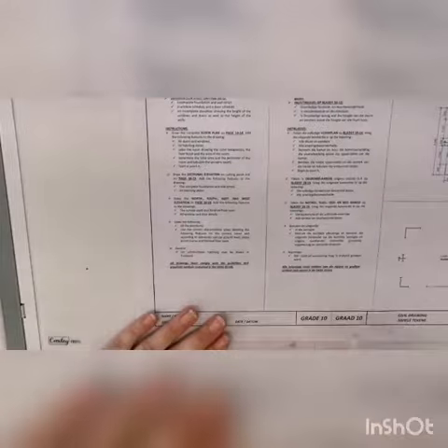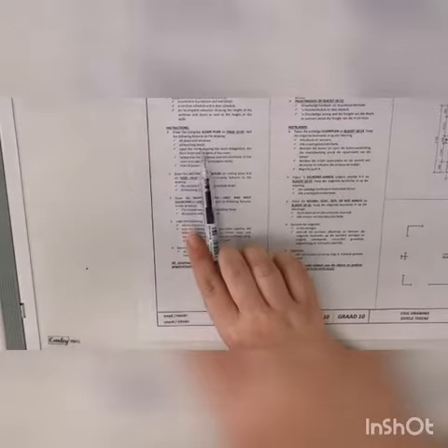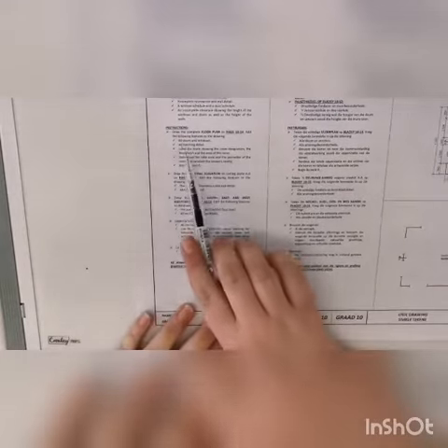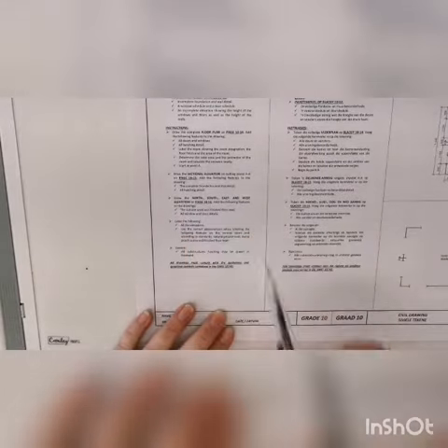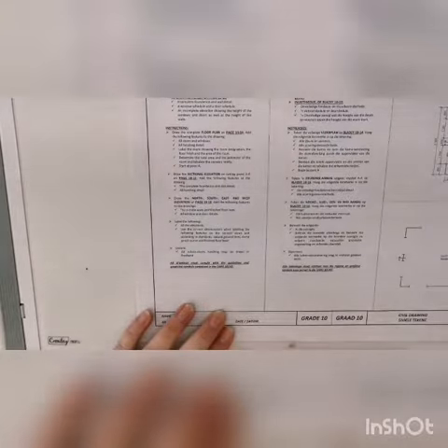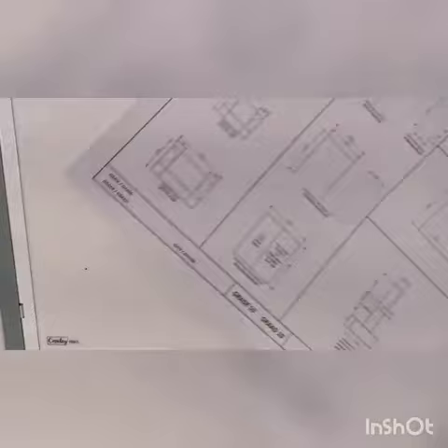Instructions. Draw the complete floor plan on page 1014. Add the following features to the drawing: all doors and windows, all hatching detail, label the rooms showing the room designation, the floor finish and the area of the room, determine the total area and the perimeter of the room, and tabulate the answers neatly. Start at point A. So let's start there.